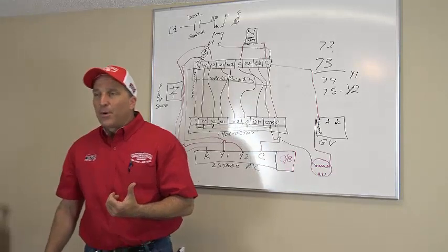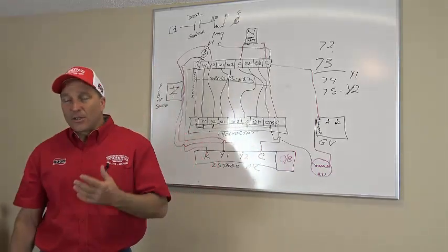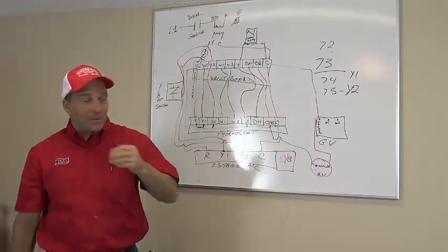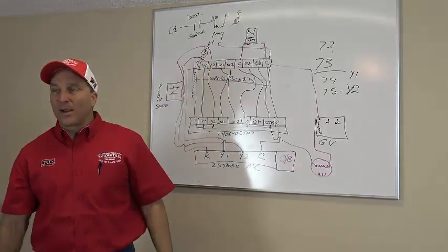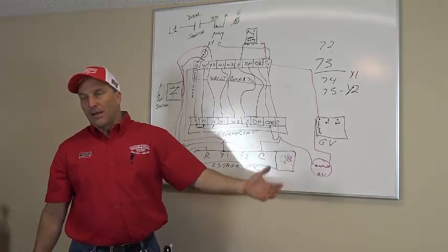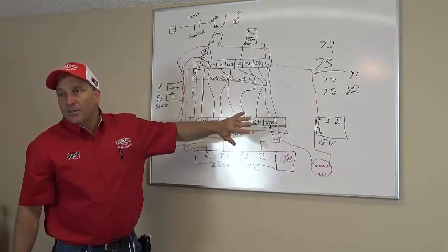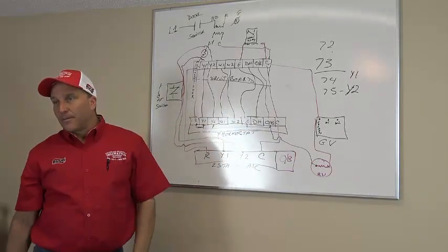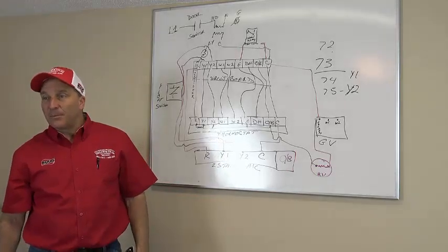Okay, can I put a two-stage thermostat on this system right now, and I have a heat pump condenser? Can I put just any two-stage thermostat on this thing? No, you need a heat pump thermostat. I have to have a heat pump thermostat.